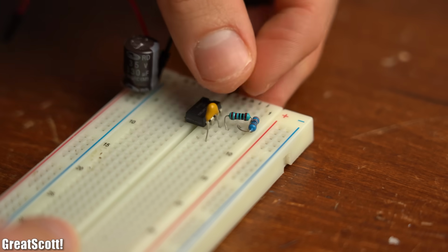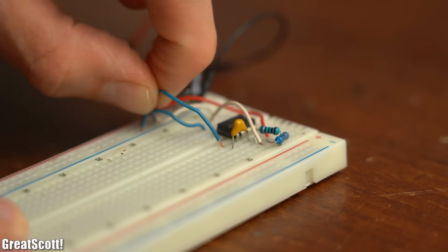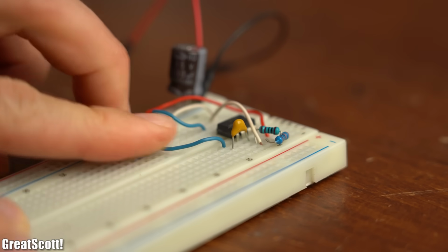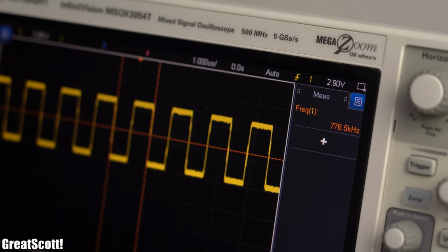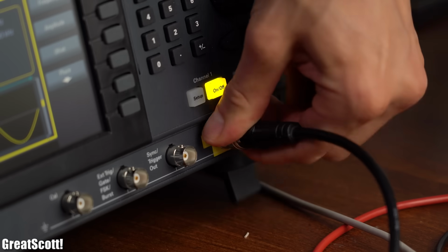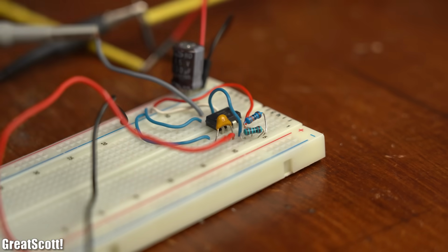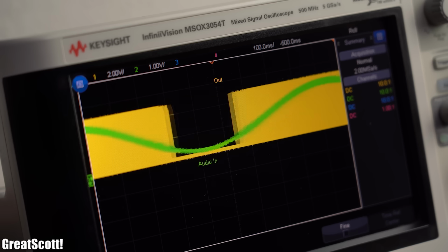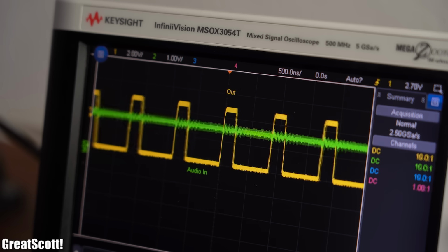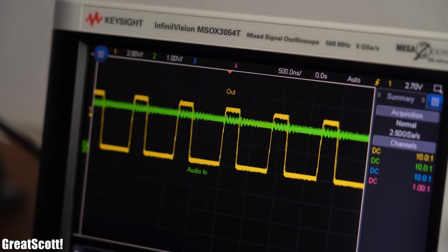So I almost didn't feel like trying out these circuits, but since they were so simple, I wanted to give them a try anyway. And after making sure that the carrier signal was created without a problem, I hooked up my function generator to firstly the control voltage inputs and saw something like this on the oscilloscope. As suspected, the audio signal does only alter the frequency over time and not the amplitudes.